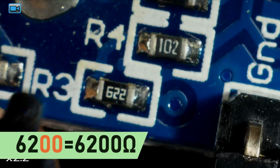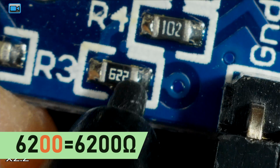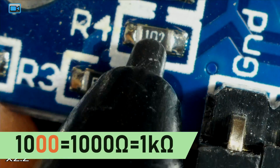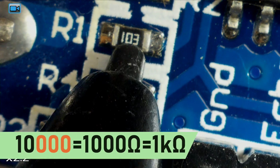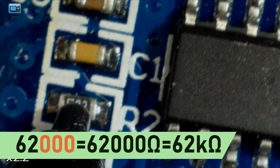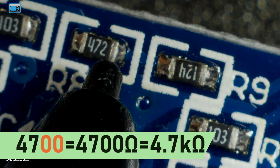As you can see, this is 6,200 because the last 2 means 2 zeros. This means 1 kilo ohm, 1,000. This means 10 kilo ohm or 10,000. This means 62 kilo ohm. This means 4,700.